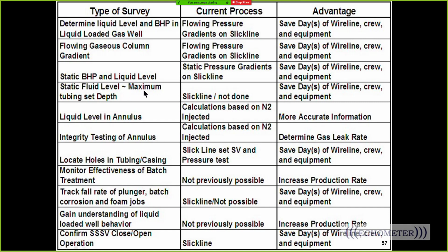Don't set your tubing below the static fluid level if you want the well to flow. You determine liquid levels in the annulus. You can test the integrity of tubing by looking for holes and things like that. You can monitor a treatment, how fast it falls down a well. If you want to keep the well closed before it's down on the formation, you can monitor the treatment with